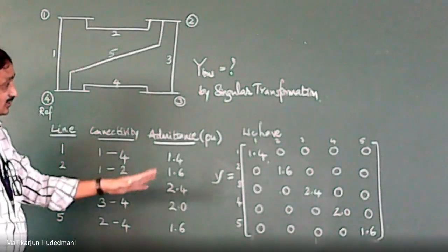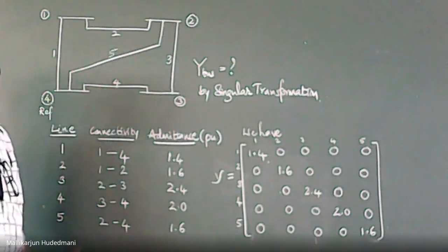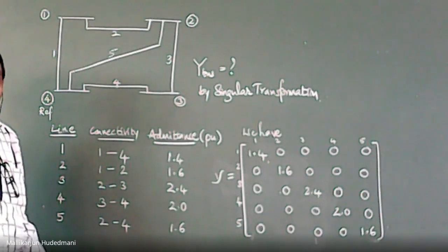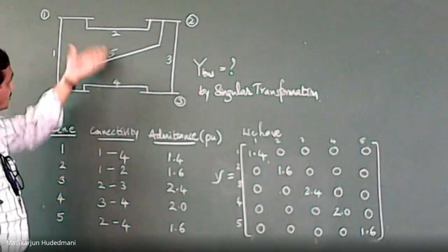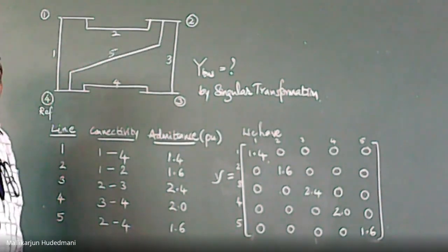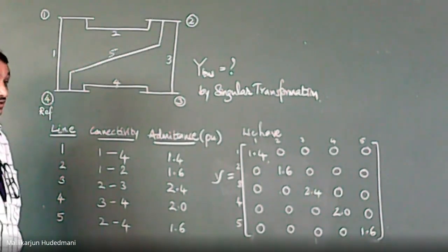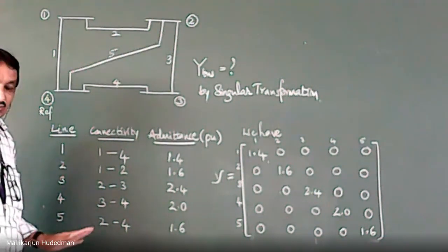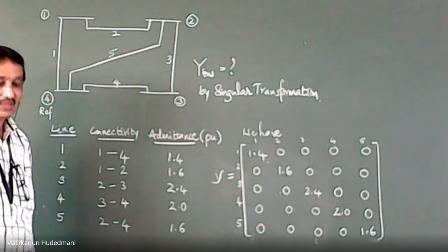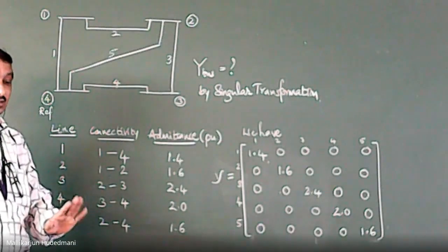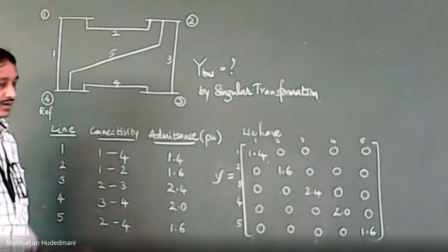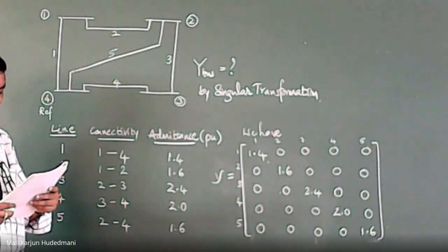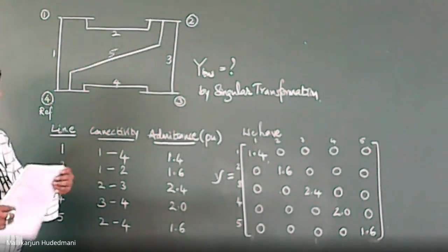Now, my next task is to obtain the A matrix for this. How to obtain the A matrix? I should draw the oriented graph. There is no arrow mentioned here. You might ask me, how can I draw? You recall back to my earlier interaction. If you have been given orientation, use it. If you have not been given orientation, you can assign one and continue till the problem ends. No question arises if there is no arrow marked. Then how to take the arrows?